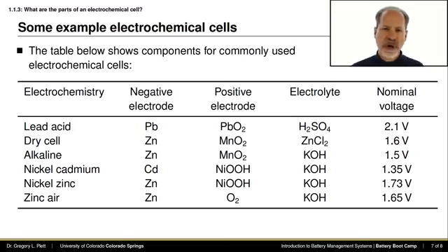Now, as you probably know, the voltage of a battery under load is less than the voltage of a fully charged battery cell that is simply resting open circuit. So the voltage depends on many factors, including temperature, and in the case of a lead-acid battery, it also depends on the concentration of the sulfuric acid used in the electrolyte. So you will sometimes see slightly different nominal voltages listed for a lead-acid battery cell in the literature, varying from around 2.0 volts to 2.1 volts.